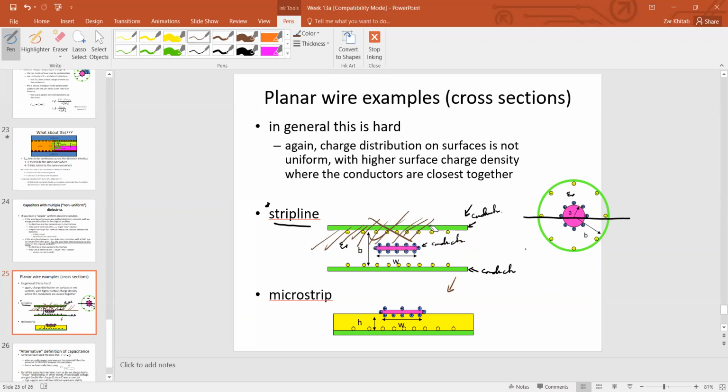You're left with this lower structure. This structure is called a microstrip. Very easy to fabricate. Typically, you etch a high-frequency PCB to end up with a microstrip line. Microstrips are used again for inter-component communication on the transmitter or on the receiver.